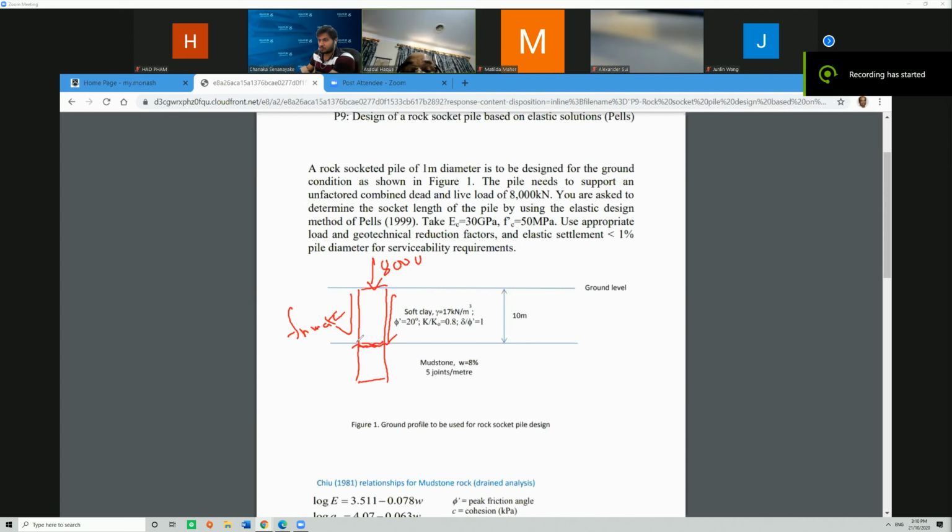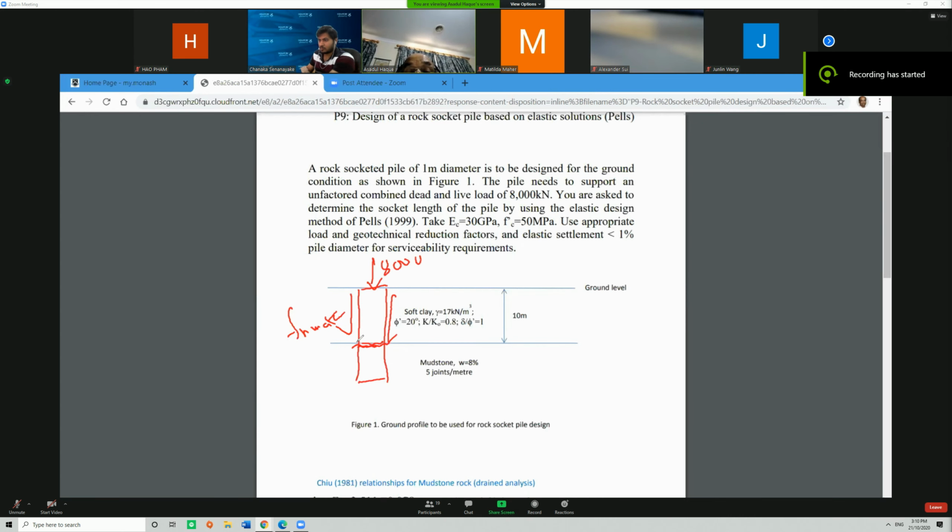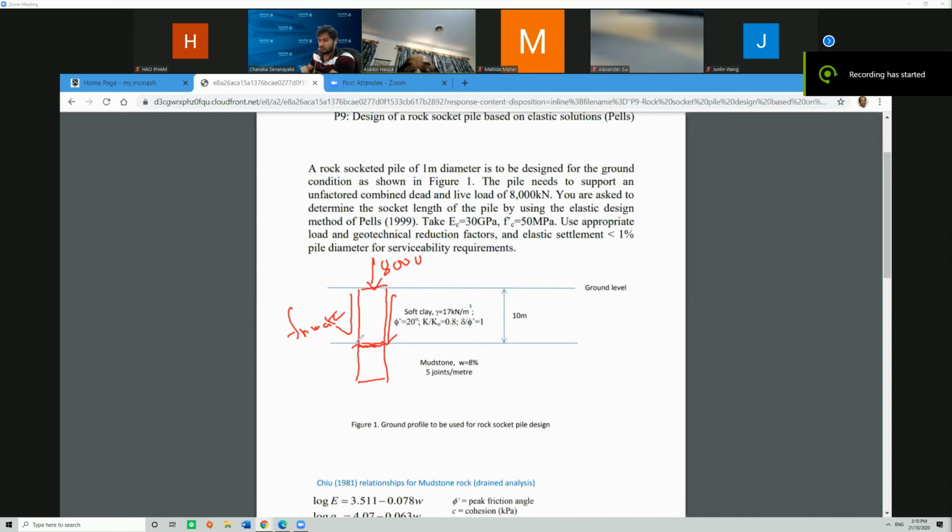What would be the bending stress, axial stress, then you can perform the structural limit state. Once you have done that one, the size of the pile is determined, the appropriate diameter. Then, if you are going to use a single pile, for any diameter greater than that, you don't have to check it again for the structural ULS.